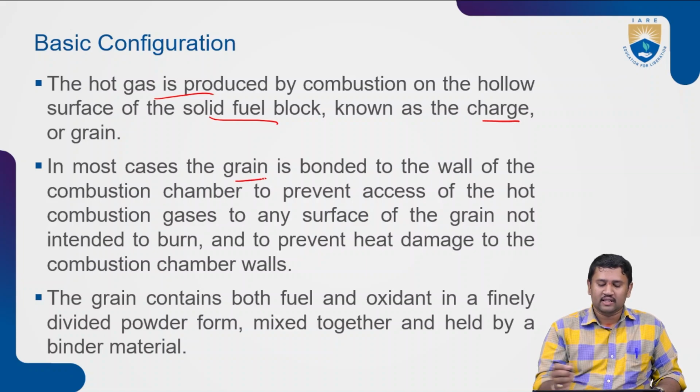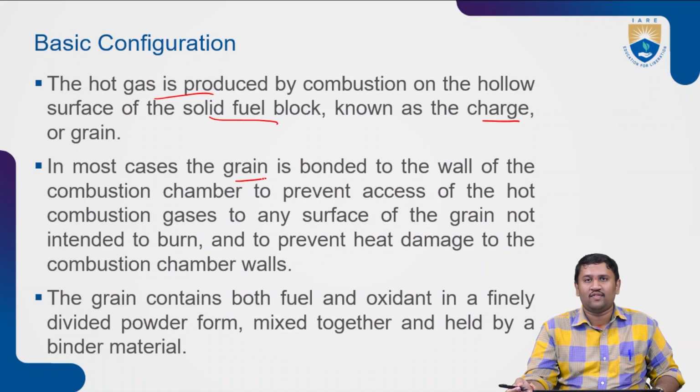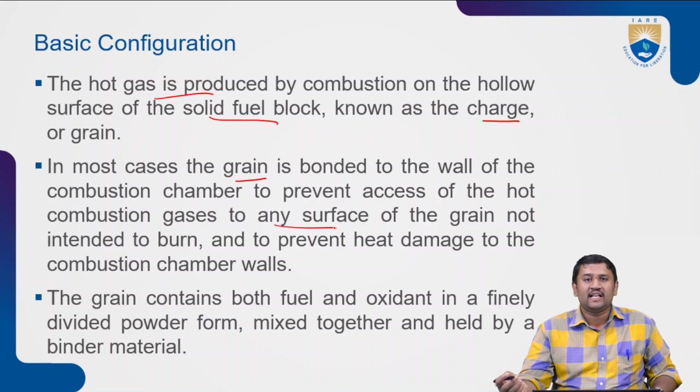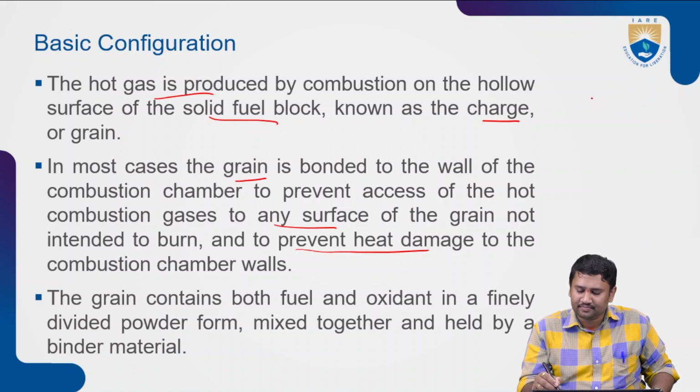In most cases, the grain is bonded to the wall of the combustion chamber to prevent access of hot combustion gases to any surface of the grain not intended to burn, particularly to prevent heat damage to the combustion chamber walls. Now, let us understand a grain.